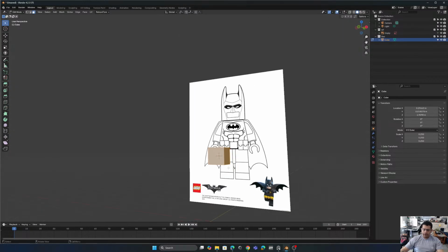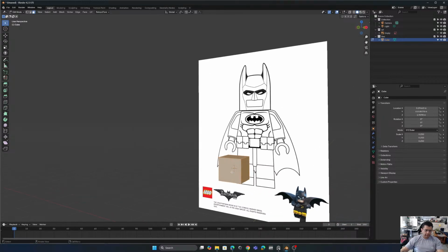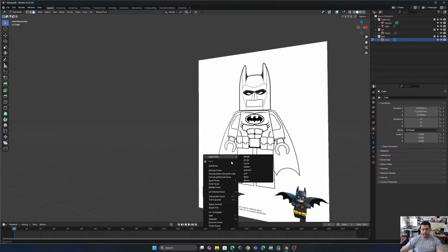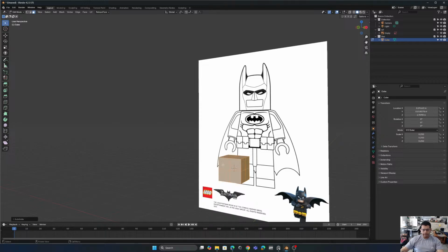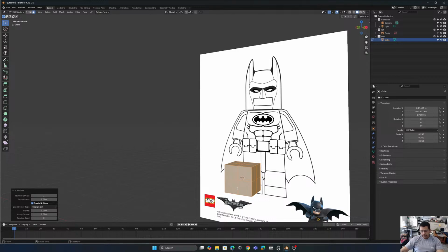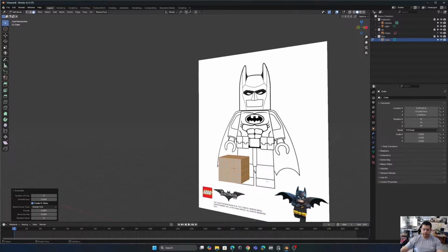Right now I'm going to create a subdivision, so I'm going to right click, subdivide, and as you can see, something appears here. So I'm going to press the arrow, and I can see how many cuts I want to get in the face. As you can see, some lines appear here. These edges are going to help us model a lot of stuff. So let's get some subdivisions here. I think with 4 it's going to be more than enough. No, 3. 3 is going to be better.